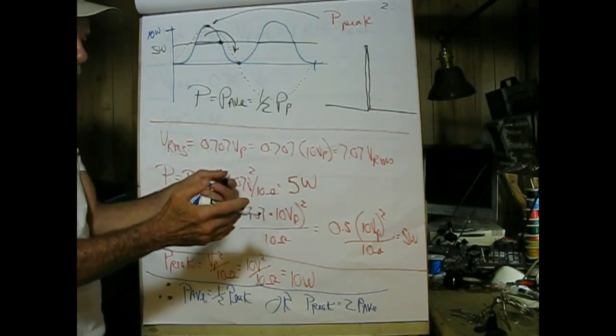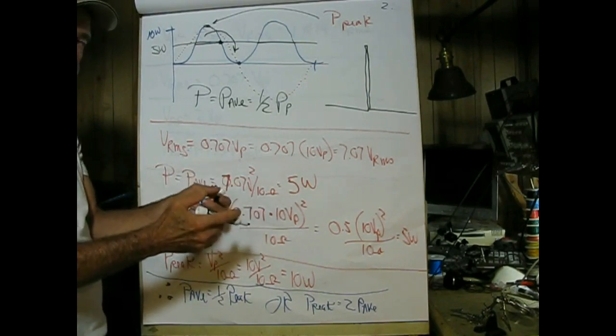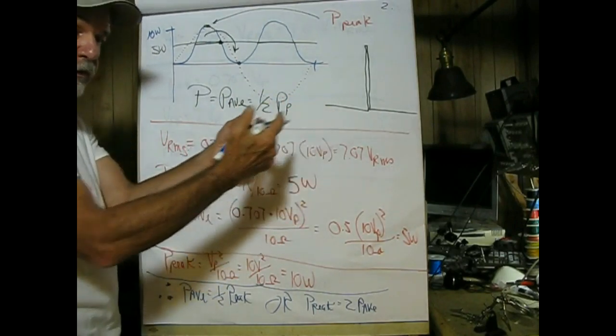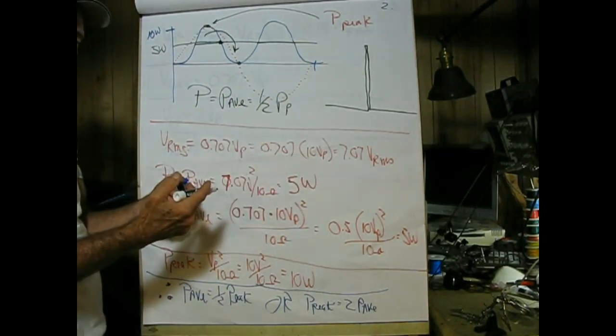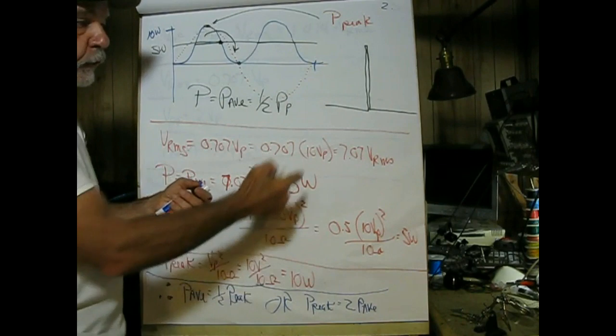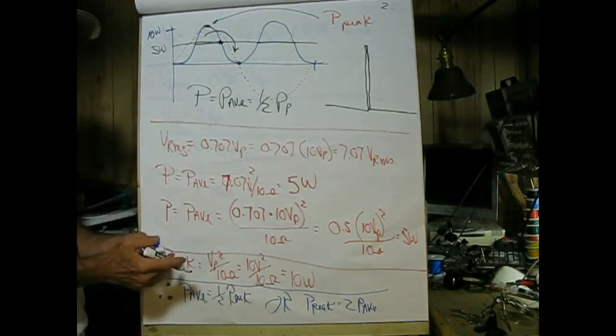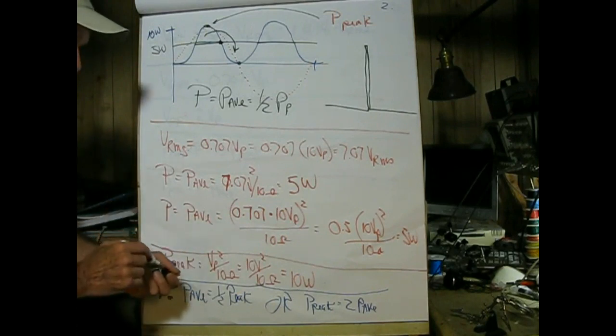If you double the distance, you have to increase the power by a factor of 4. Then it hits an airplane and radiates back, double the distance, increase the power by 4. So to double the range of a radar, you have to increase the power by 16 times. A little bit off topic.